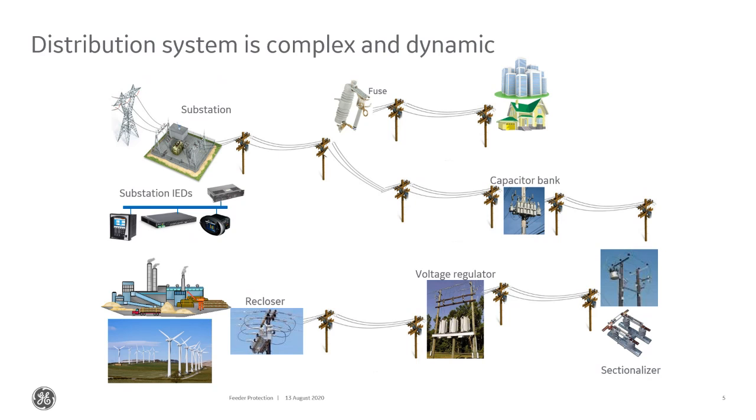So some of the equipment, you're probably familiar with a lot of these pieces of equipment that we generally use in the distribution system. The fuses we talked about, so you might have a branch circuit of fuses protecting that branch circuit. You might have capacitor banks for voltage stability, right? If you have a long feeder going from the substation to some rural area, because of the voltage drop across that long feeder, the end user might see low voltage. So you might need to supplement that by adding capacitor banks to maintain voltage stability.